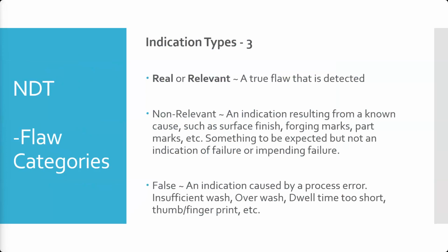Okay, an example that we had to do regularly: we had to do dye penetrant inspection on our turbine cases on our engines. They were prone to cracking at the 3 o'clock and 9 o'clock positions, the two sides. They were allowed to have cracks of a certain size, up to about 2 inches long.